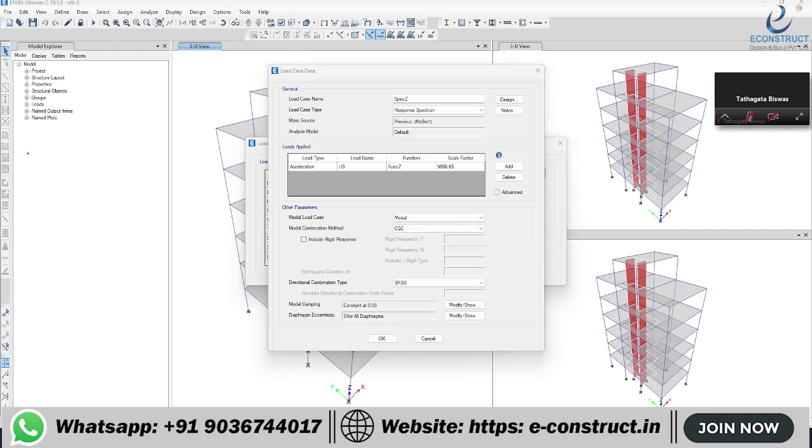But sir, in the first case you told that it is z in the scale factor. So what is the formula for VB? AH into W. For VVZ, if we talk about it, then also it is AV into W, right? W is the seismic weight, and that seismic weight is anyway given by the mass source. Now this AV, ultimately, will be multiplied by g, the entire thing, to get you the actual base shear.